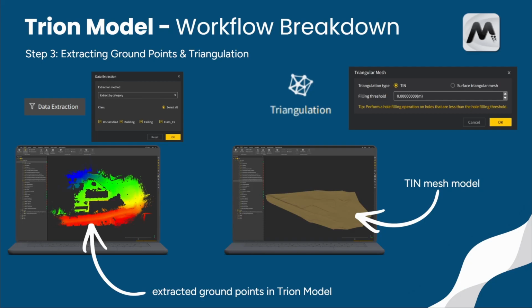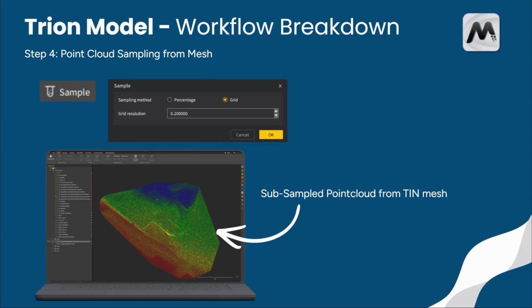And if needed, we can first reduce the point density slightly by using the sample function. This helps the generated mesh to be lighter, reduces file size, and avoids unnecessary strain on computer resources. Once the mesh has been created, we then use the subsample function to generate a new point cloud on the surface of that mesh.